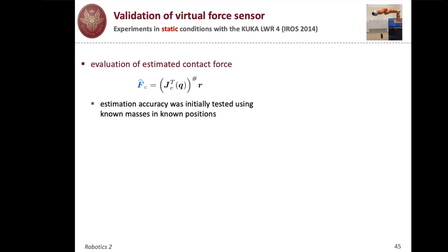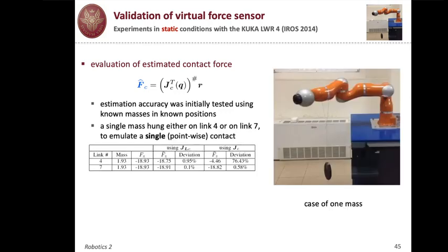You can use a force device for measuring object. We decided to use a known mass located in a known position, like you see on the top image, which is now reported here in large. So we have a known mass appended to the robot in a known position. We multiply the mass by the acceleration of gravity, and this gives the force applied to the structure.